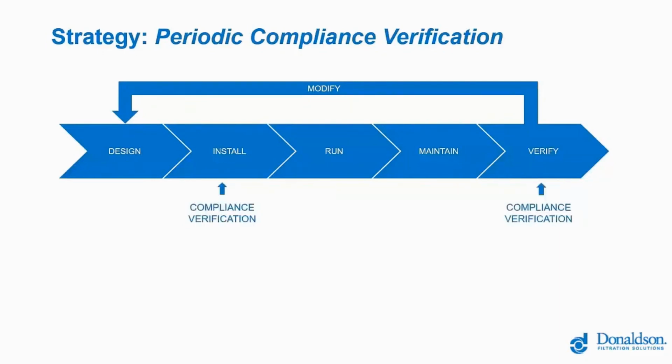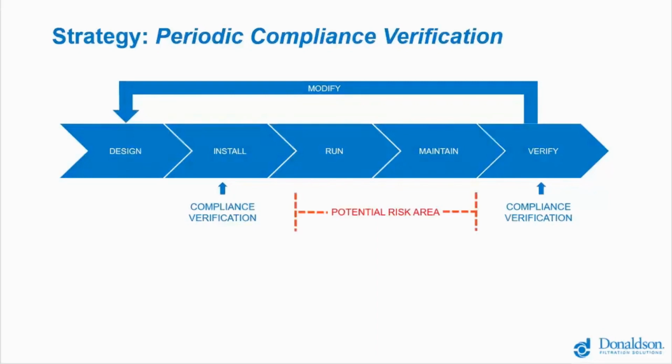So when we want to make sure that our dust collector is working the way it's designed and that we're within compliance of all of our regulations and our internal processes and procedures, we're typically going to do that anytime we install the dust collector or make a design change to it, and then when we get to that verify step at the end. And that verify step might be every few weeks, every few months. It might be up to a year, depending on what regulations you're required to meet or what your internal processes require.